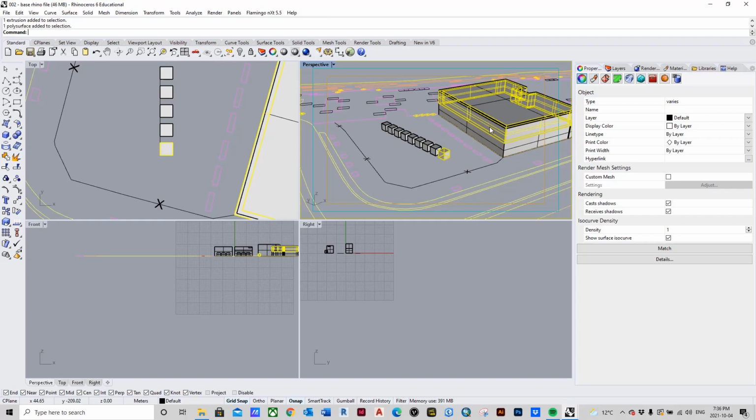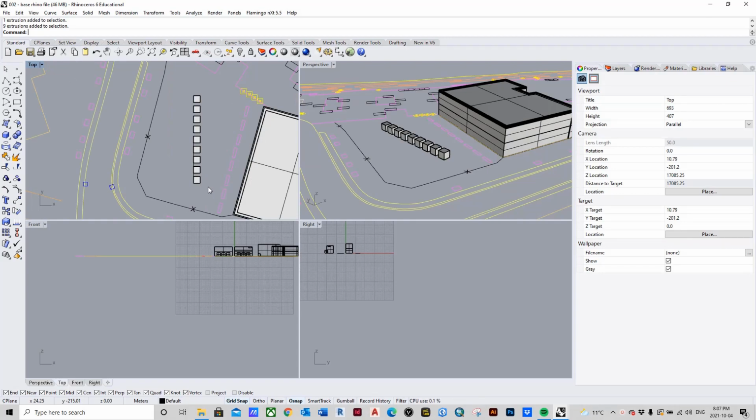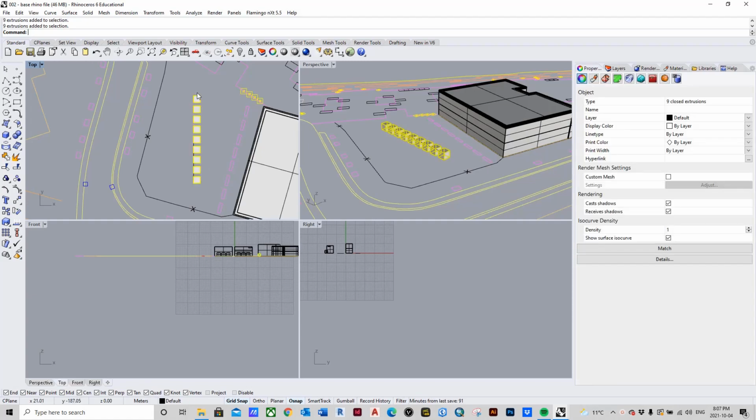So this is where, because it needs to be lined up and touching, I'm going to teach you how to use the rotate tool. So now that we've got a linear array of these cubes that we're going to use for a Boolean difference, now it's time to show the rotate tool. But first, we're going to get these where we need them. So why don't we click and hold left click. We're going to do a select box in this view, release, and now we've got them all selected. Now we need to move these up to the face that we're going to rotate them to be on the same face with. So let's do that right now.